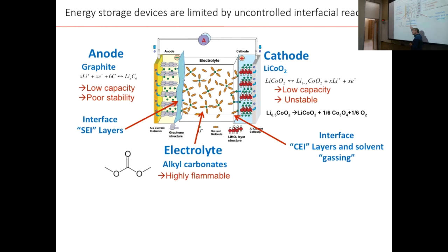So the manufacturer does this for you already, but just to be sure that it's really good, you charge it up all the way the first time. And by the way, the reason that you should never discharge a lithium-ion battery all the way to zero is that this layer begins to degrade when you completely discharge the battery, and it won't reform properly, right? So that really is the key to the stability of the battery.